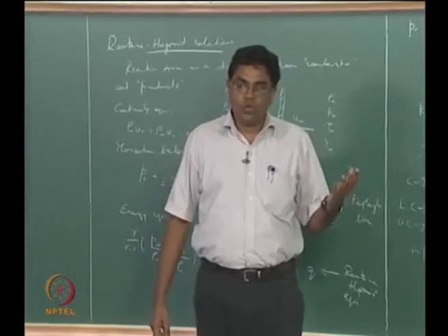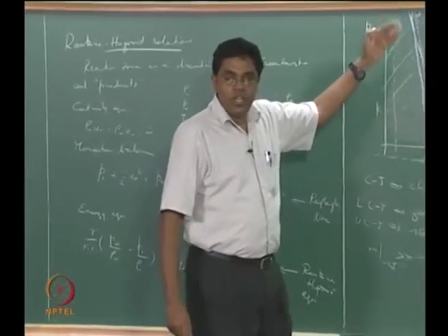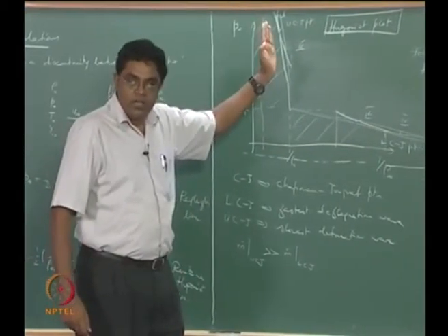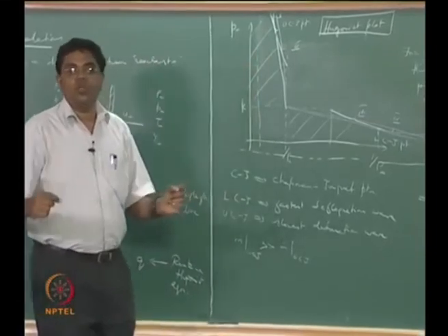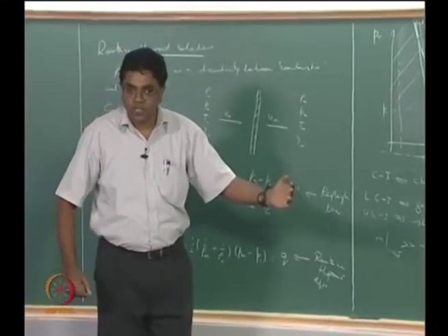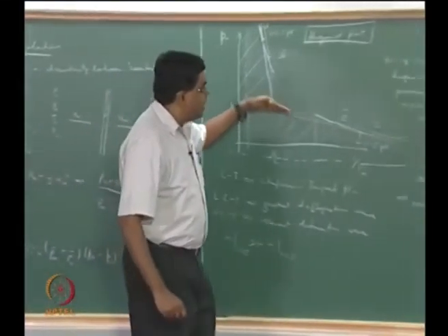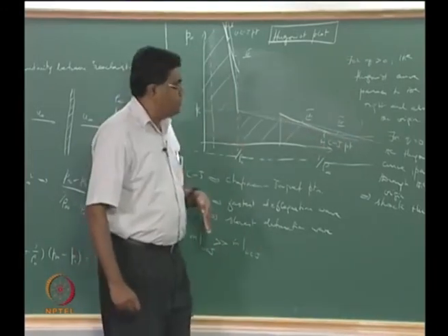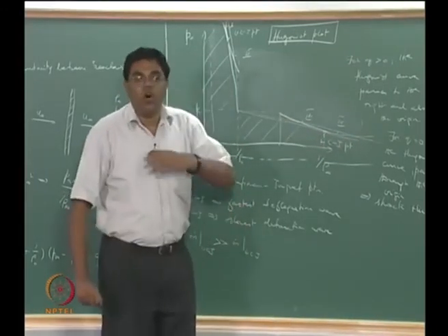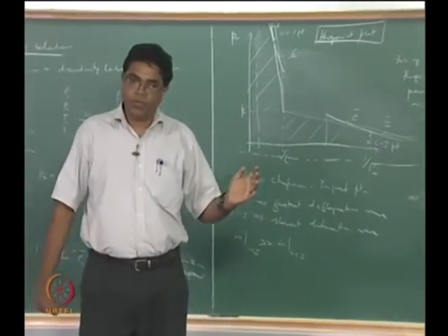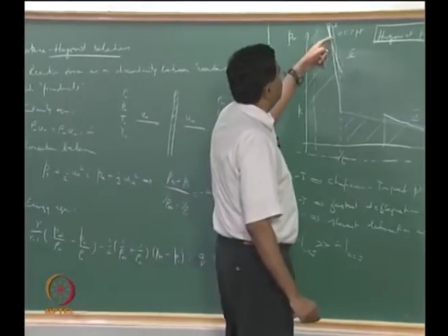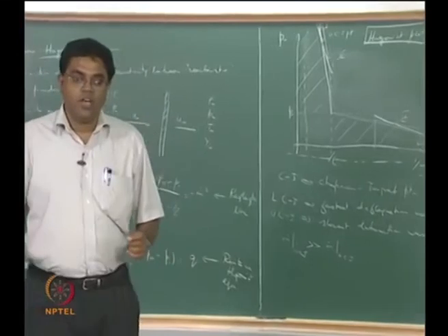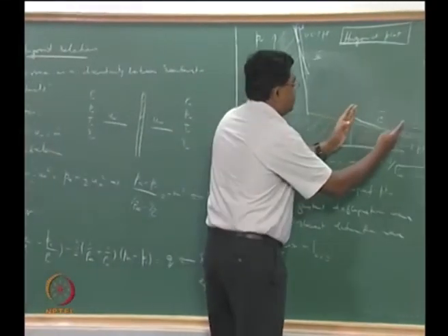The way I would show this is to consider the CJ detonation and the CJ deflagration. I would like to show that the CJ detonation is supersonic, which means the slowest detonation is supersonic. That means all of the detonations are going to be supersonic, and I am going to show you that the fastest deflagration, the lower CJ deflagration, is going to be subsonic, therefore all other deflagrations are subsonic, right? And then we will also consider the downstream Mach numbers for the UCJ and the LCJ and show that they are actually 1, thereby we can clearly see how these things are demarcated, right?